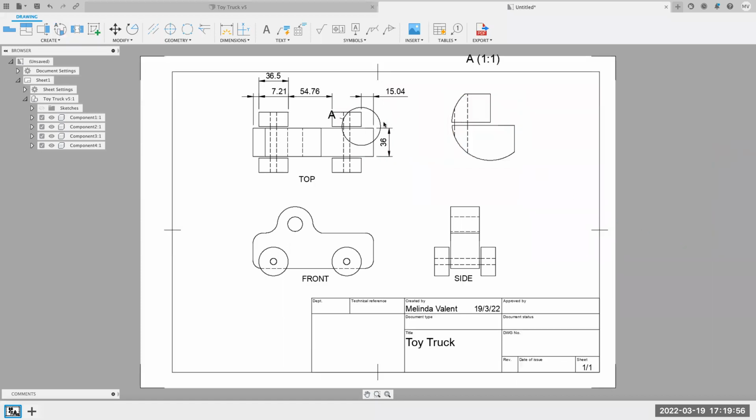So there it is. You can see A, and it's been labeled here. It's been taken off the page. I need to keep that on the page, very important. Now what I can do is I can pop a dimension on this point from this point to this point and show how that is 2 mil apart, which would have been very, very difficult on a 1:2 scale, but on 1:1, you can see that that's a lot easier to dimension.